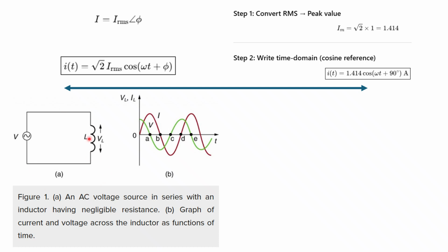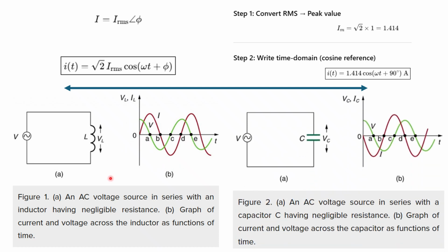So in case of the inductor, you can see here it is cos and 90. Your current is actually lagging and your voltage is leading here, right? So since voltage is leading, now exactly like that you are going to represent your reactances. So you can write XL is equal to omega L, and we are also writing j omega L because it has the voltage leading. If you are going to write it, then you have to write the j because the voltage is leading.